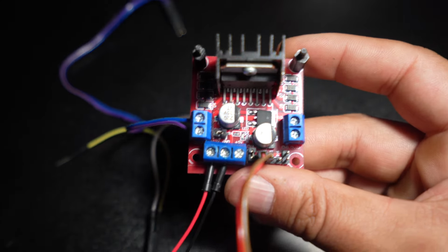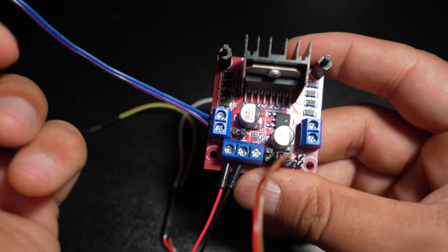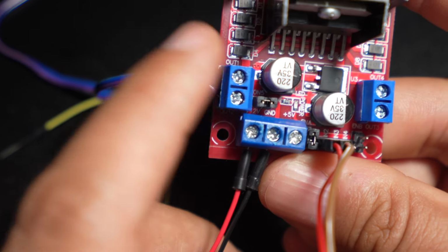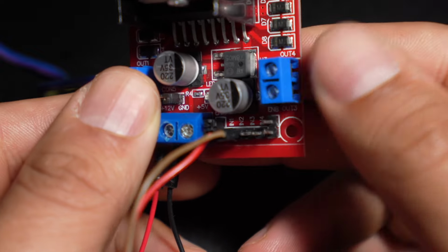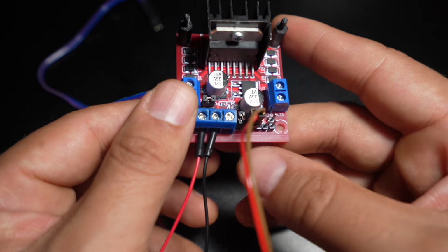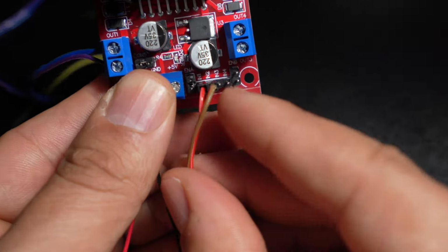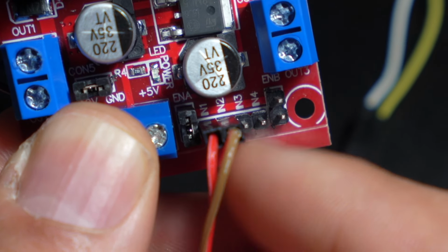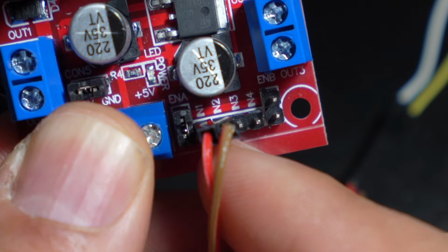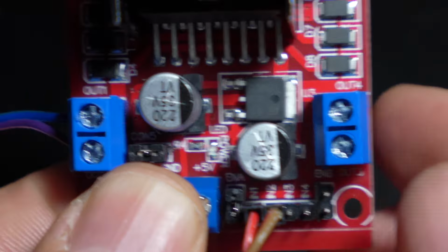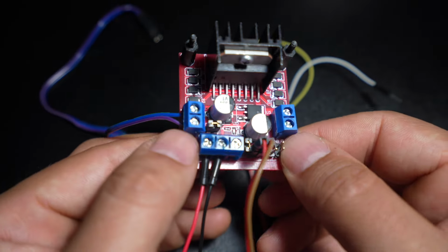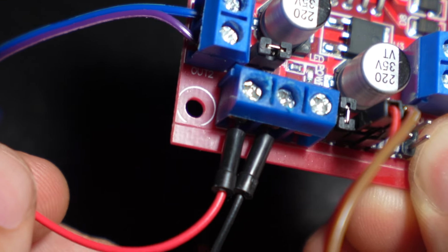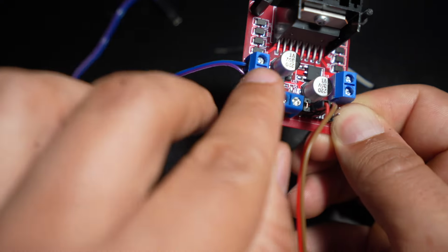This is the dual H bridge that we're going to use, and it is dual because you can potentially control two independent devices. You have output 1 and 2 on the left side and output 3 and 4 on the right side, and these can be independent devices. You use these 4 inputs to control the H bridge. So 2 H bridges: input 1 and 2 control one of the H bridges, and input 3 and 4 control the other. The last thing that you need to be aware of is that you power your high current or power electronics with these 2 terminals.